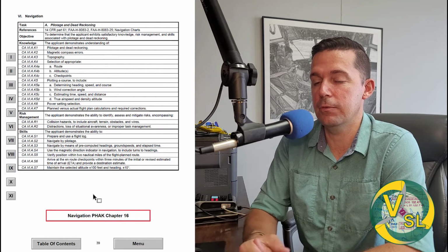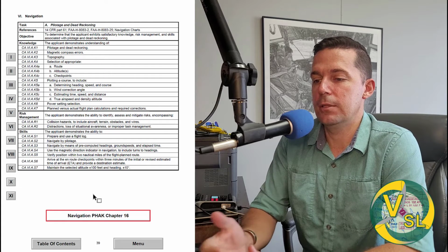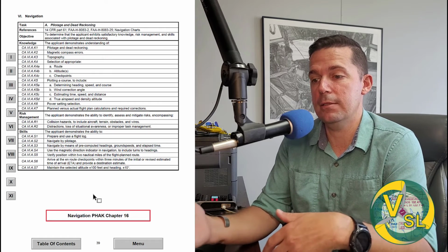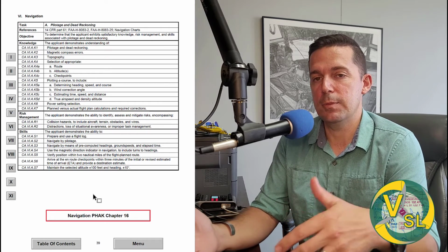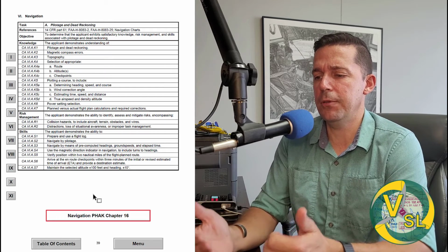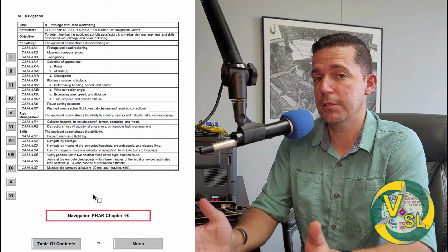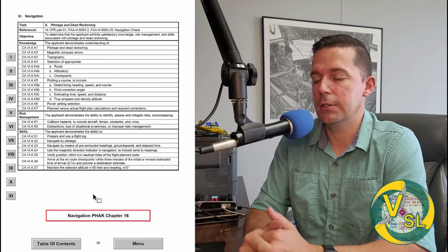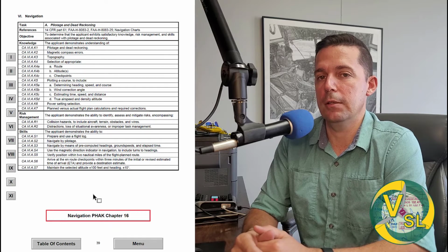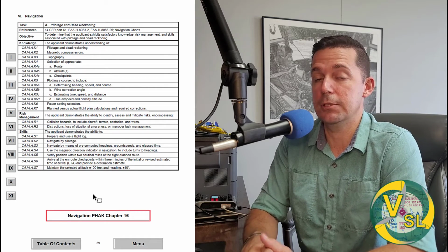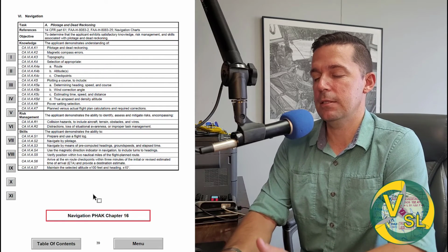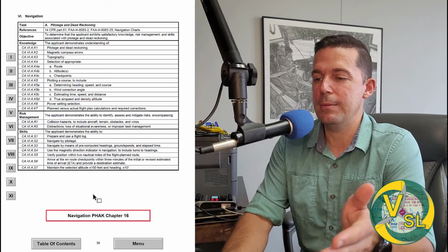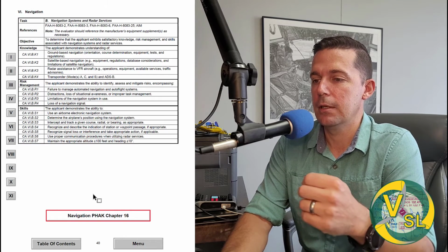I'm going to ask for your nav log before we even go to the airplane. Then you're going to be able to use dead reckoning and pilotage. So pilotage, looking out the window, dead reckoning, that's your pre-computed headings, ground speeds, and elapsed time. You need to do both of those to verify your position within 2 miles within 3 minutes. So that's kind of plus or minus 3 minutes, plus or minus 2 miles. Those are the objective standards here, plus or minus 100 feet, of course, and plus or minus 10 degrees of heading. Pretty basic. This is a lot like what we covered in the private pilot. It's just, I believe the private pilot was 3 miles in 5 minutes. This is 2 miles in 3 minutes.